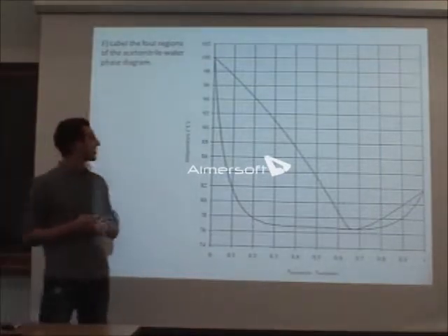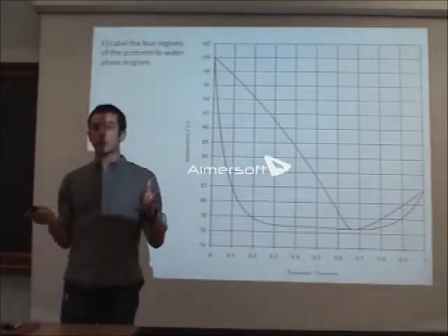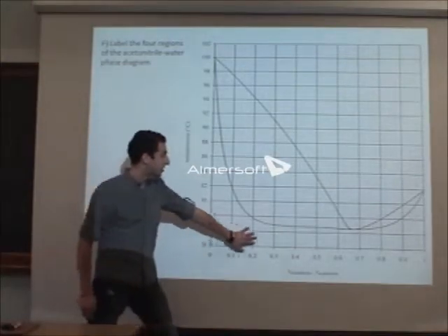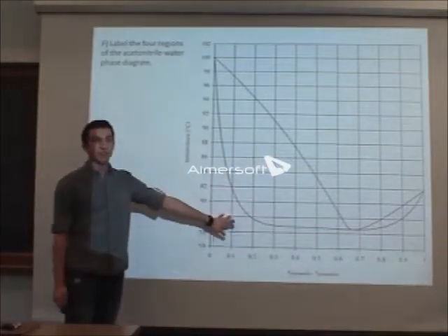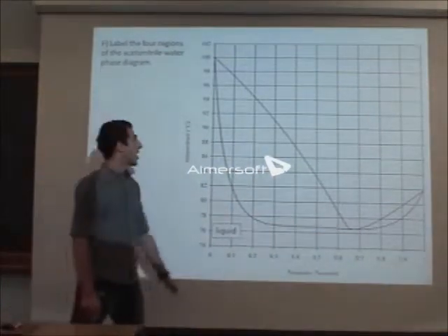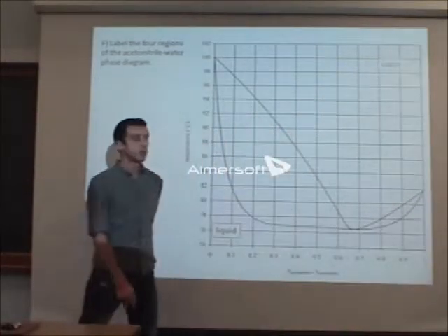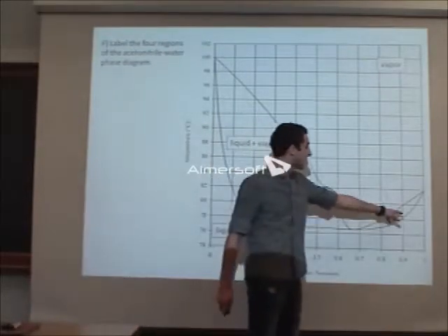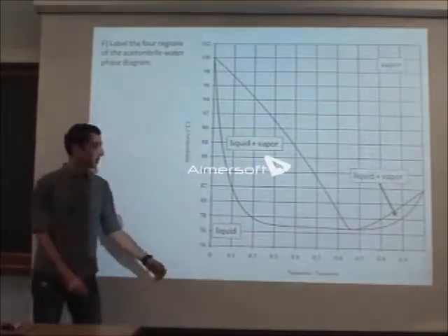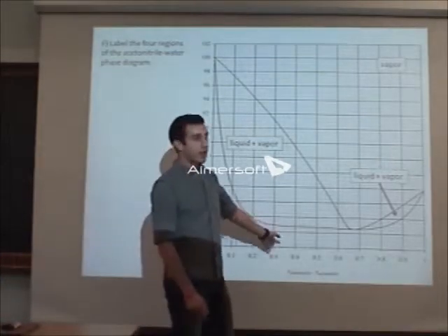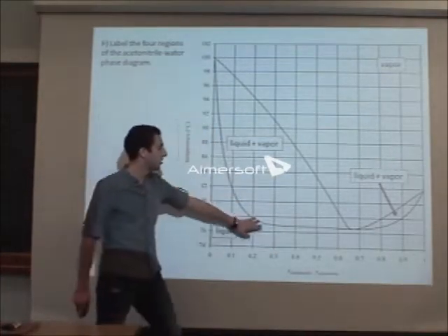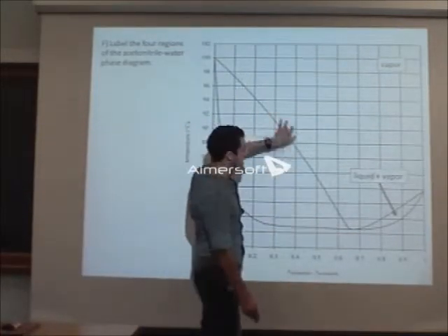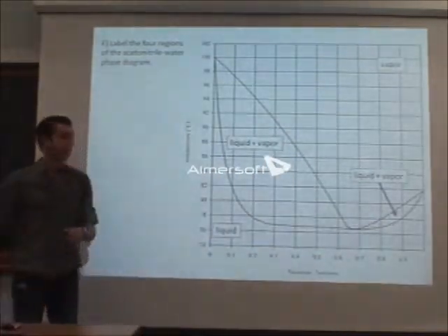All right, switching graphs. Now we're on a temperature-composition graph. So like was said in the previous presentation, this phase here at low temperatures is going to have to be liquid. At high temperatures, we want vapor. That should make sense. And in between, we'll have liquid-vapor equilibrium in each of these pockets. So if we start at a liquid here and go up, we'll hit this curve, which will be the bubble point of the mixture. If we start at a vapor and go down in temperature, we'll hit this curve, which will be the dew point of the mixture.